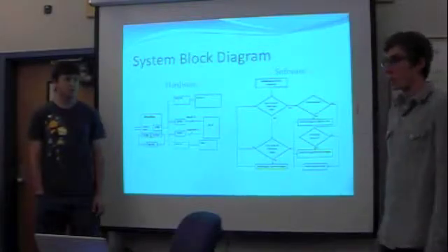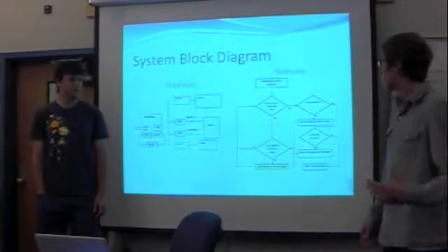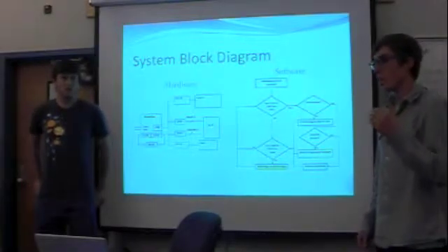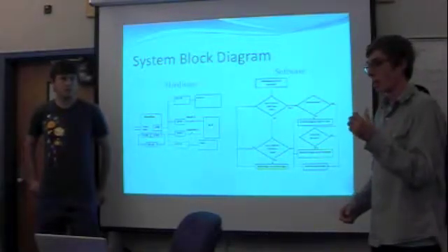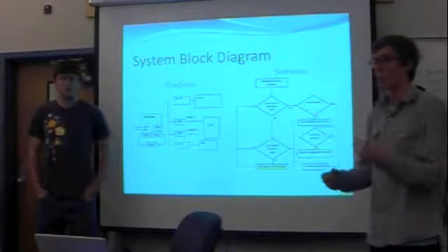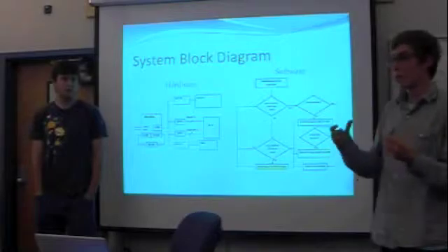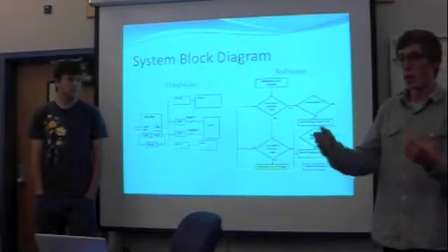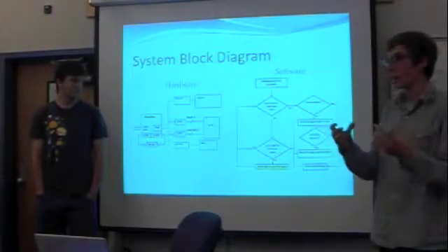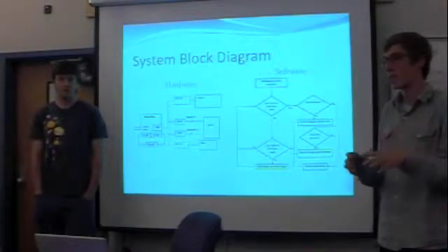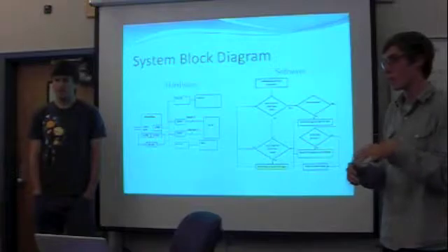In order to keep track of what was happening, we needed to have two loops reading the registers. Actually, one's checking the keyboard input and one's checking the Xbee input. If we had input from the keyboard, we'd process that character and it'd go through a whole conversion code, because the keyboard actually sends not ASCII, so you have to convert that to ASCII.